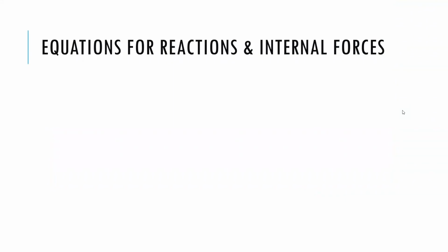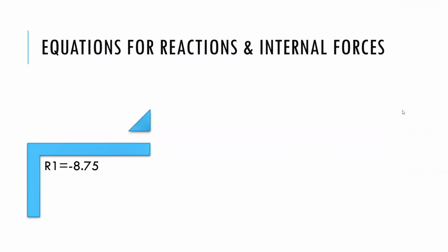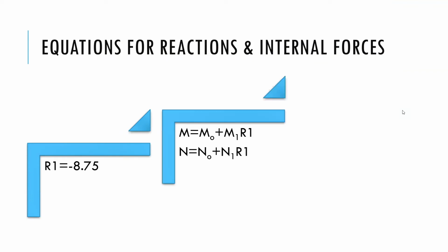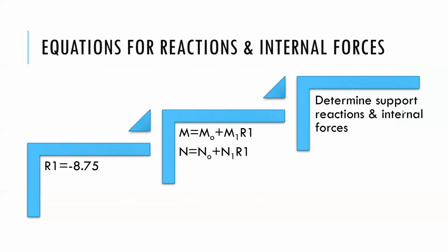Once we have solved for the redundant force, we can determine the remaining outputs such as support reactions and internal forces by just using the equilibrium equations. We can also use the shown equations to solve for the bending moments and axial force. They can be used for support reactions too.